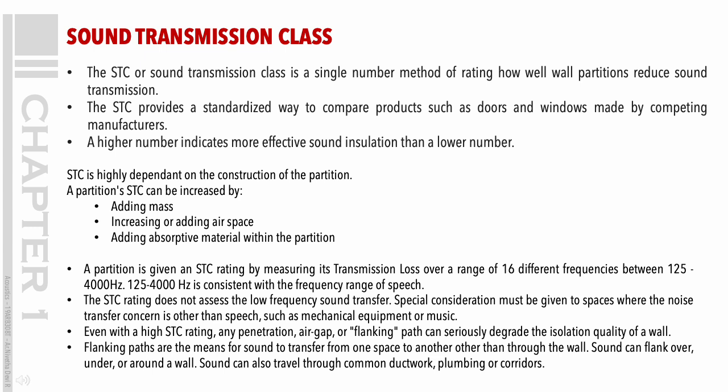STC is highly dependent on the construction of the partition. A partition's STC can be increased by adding mass, increasing or adding airspace, adding absorptive material within the partition. A partition is given an STC rating by measuring its transmission loss over a range of 16 different frequencies between 125–4000 Hz. 125 to 4000 Hz is consistent with the frequency range of speech. The STC rating does not assess the low-frequency sound transfer.